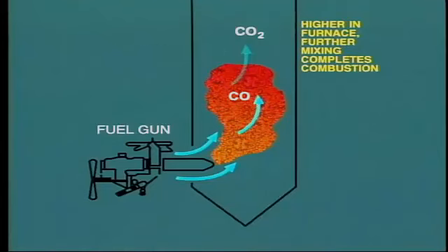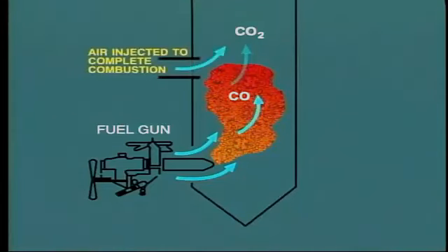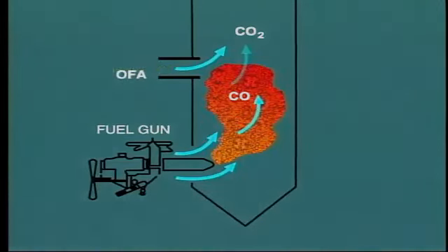In fact, in many boilers, a portion of the combustion air is injected at a point higher in the furnace in order to assist in completion of the combustion process. This air is generally known as overfire air, or OFA.